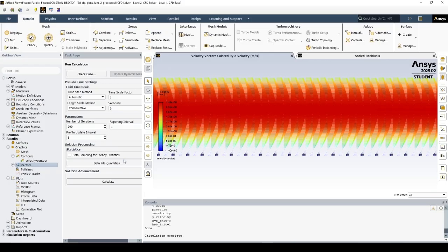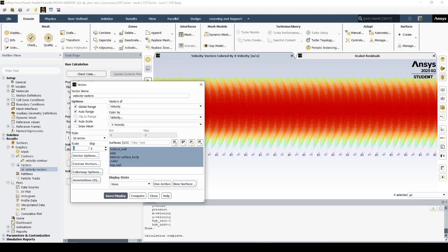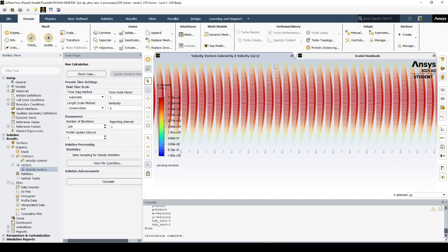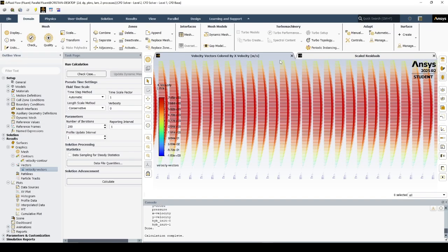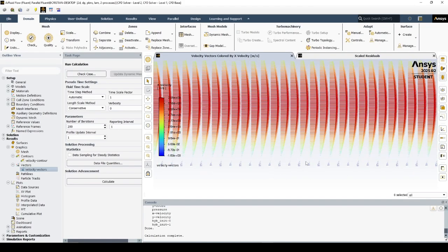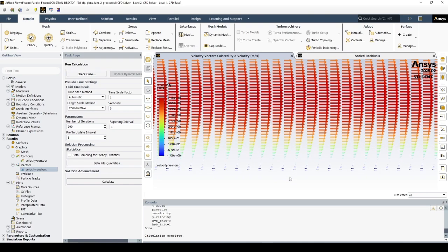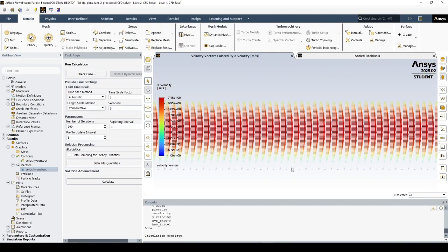It's a little bit difficult to see at times, so what you can do is change the scale. Like, let's say half the scale. Save and display. And now they're not all jumbled up. You can see my velocity vectors as they go. This represents the moving wall or the moving plate at the top, going at some speed, and it keeps increasing. But then at some point toward the bottom, it actually reverses so that the bottom plate is going -2 meters per second to the left.